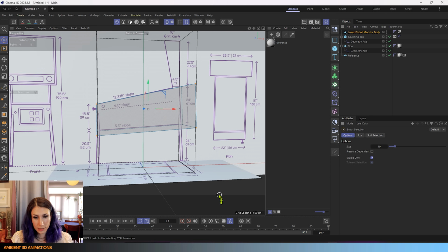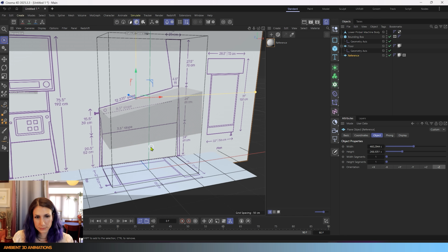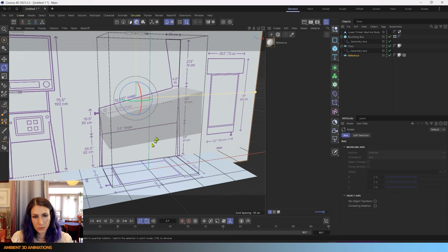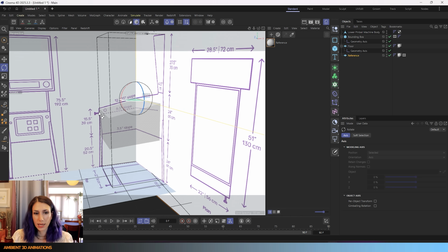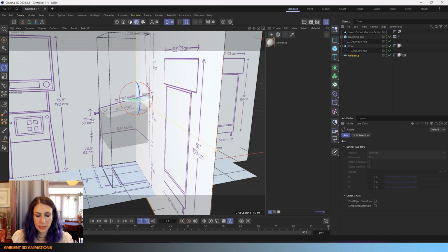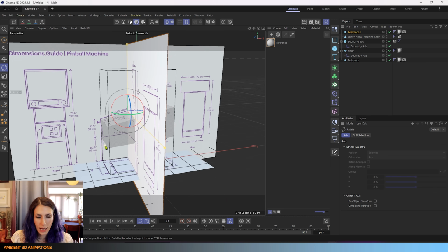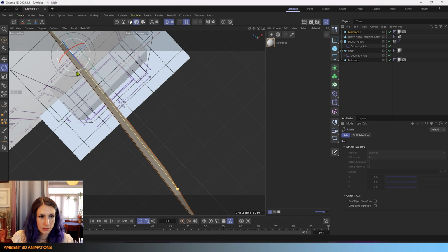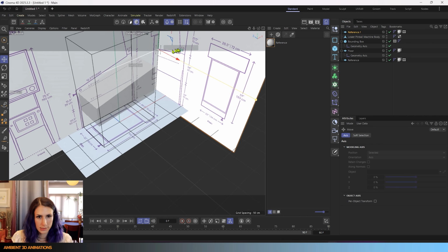The next step is we are going to build this part with the screen on it. So we're actually going to need another reference for this. So I'm going to just go ahead and click on this. Hit R, hold Control, so we're making a duplicate, and I'm holding Shift so that at the same time as doing that, I'm using Quantize, and I can rotate in increments of 5 degrees, since that's what we have our Quantize set up to. I think that's 90 degrees. No, it's not. Move that around. It's hard for me to see the dimensions sometimes on the screen. It's a little small.